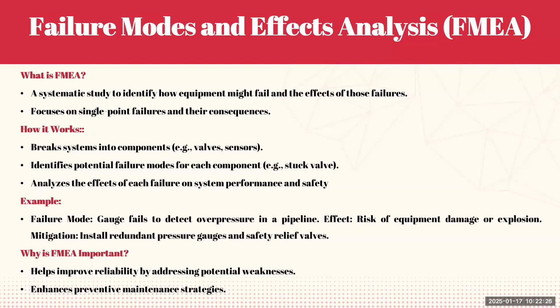Then it identifies potential failure modes for each component. Let's say the valve is stuck, for example, that's a failure mode. Then it analyzes the effects of each failure on system performance and safety. So let's take an example. Let's say the failure mode is a gauge fails to detect overpressure in a pipeline. The effect is a risk of equipment damage or explosion. The mitigation is to install redundant pressure gauges and safety relief valves.